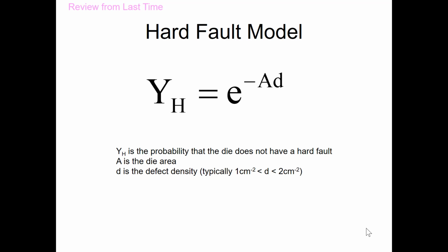These dust particles are really small. But if a dust particle was 1 micron in diameter, and your device dimensions were a tenth of a micron or smaller, that dust particle might wipe out a whole bunch of circuits. Consequently, a dust particle as small as the size of a transistor, or a fraction of the size of the transistor, could cause failure of a circuit as well.